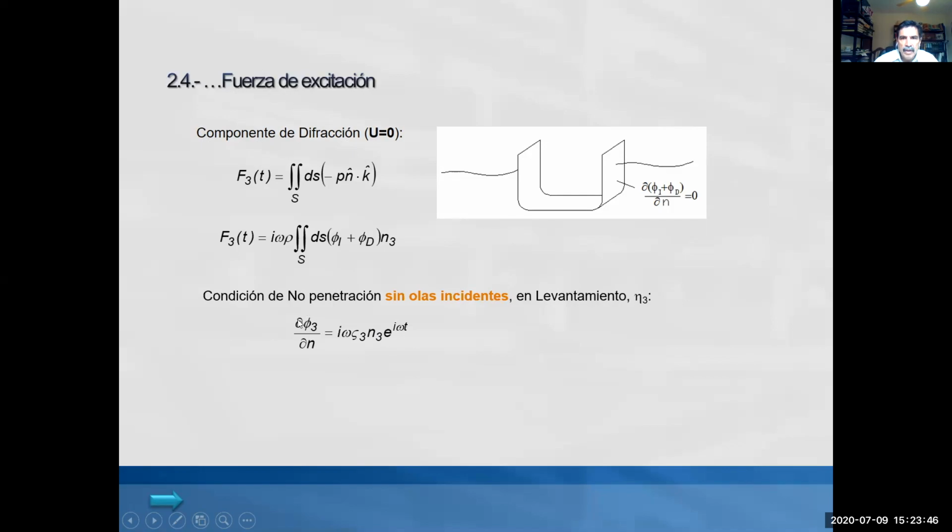In this problem, we have the opposite. The ship is moving, and because of this motion, some waves are getting away from the ship. In this case, in the excitation, the ship is fixed and the waves are reaching the ship. So we saw some similarity. And what people did was, let's try to use the solution of this problem in order to solve the excitation problem. So this is coming from the previous problem. In that case, the ship was moving, but no waves were incoming to the ship. Okay, so this is already solved.